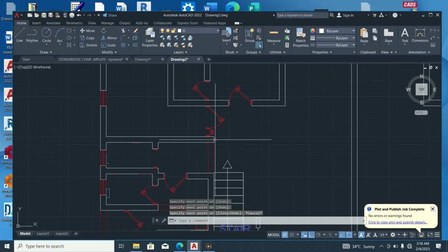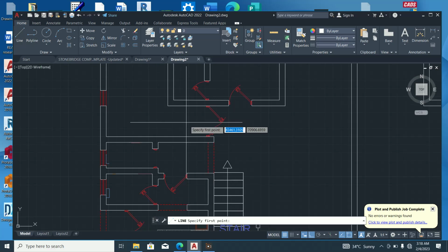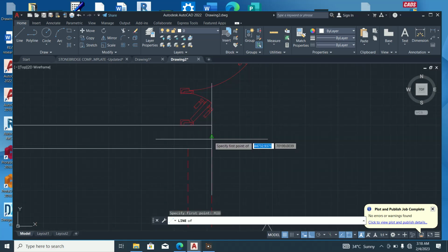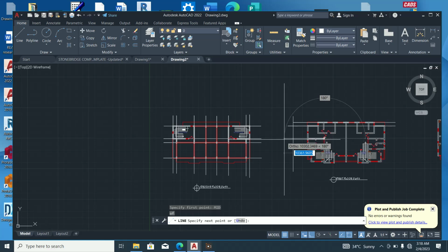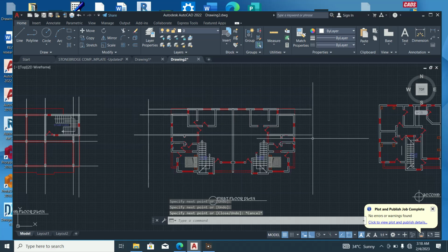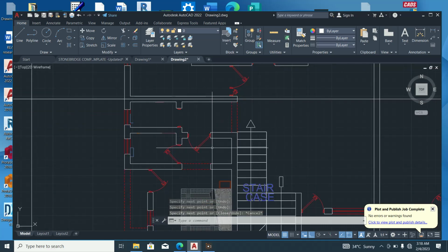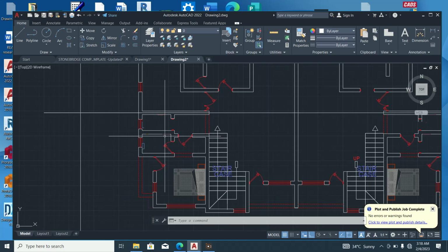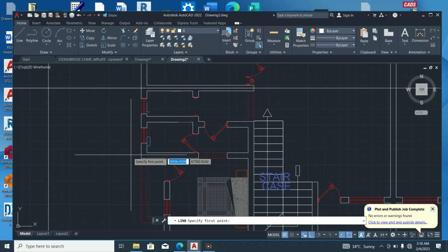Same thing here, we can easily get it here. You pick a line, you type mid. Sorry, this is not mid. Okay, mid and press enter. We'll get it at this point here on your line. I'll pick a line again. I think with this partition wall, we might not need a beam here because it's a partition wall. So you can just jump to the other line. From experience, I've gotten to know that.